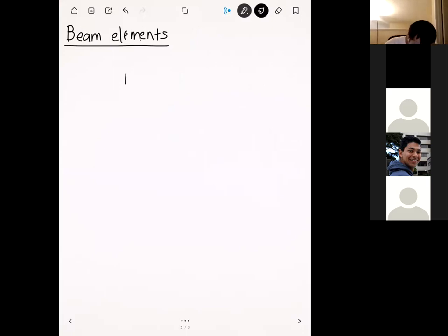To refresh your memory, springs and trusses look like this, a slender element like this, and they are known for deforming like this. They're only known for displacing axially, which is down the length of the element. What results from that is that truss elements are either in tension, where they're being pulled apart, or compression. And with truss elements you can make a lot of really complex structures.